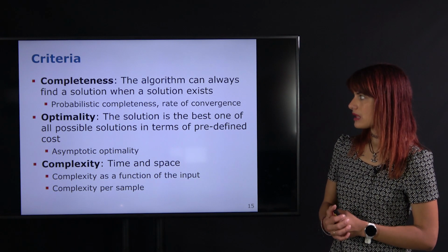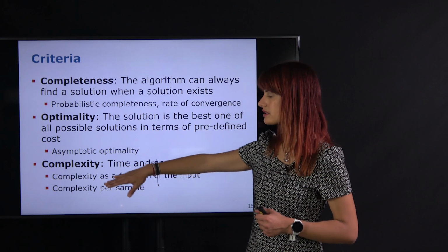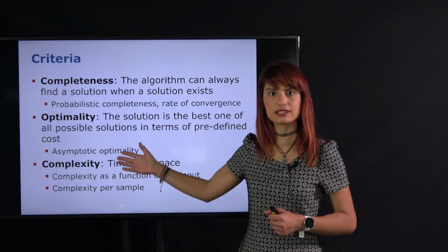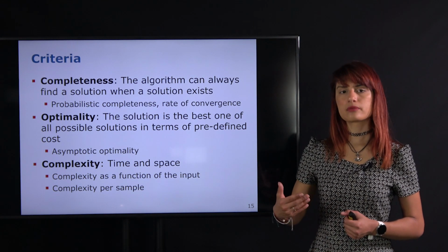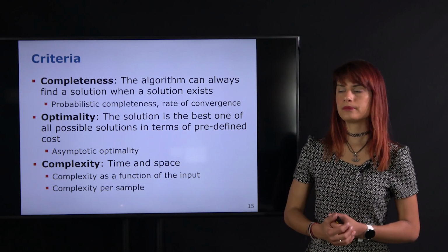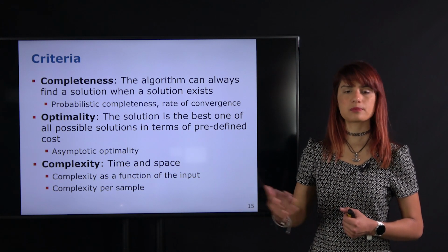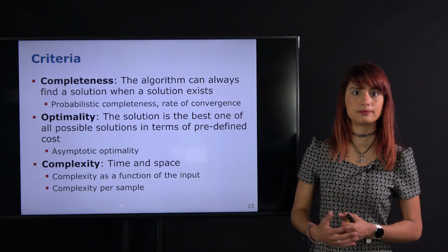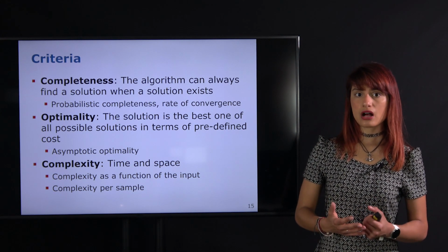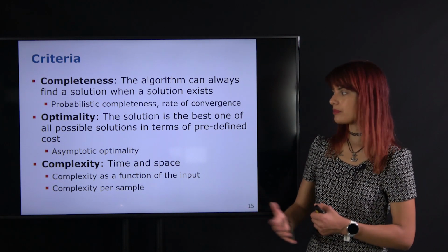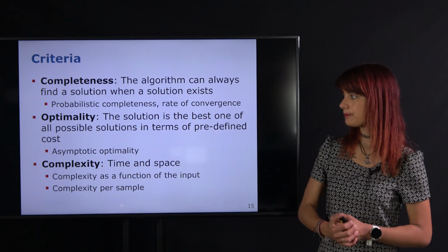For sampling-based planners, an analog of probabilistic completeness here is asymptotic optimality. So if we sample more and let our algorithm do more work in more time, does the probability of finding the optimal or the best possible solution approach 1? This implies that our algorithm is actually improving the path over time if it can converge to the best possible one.